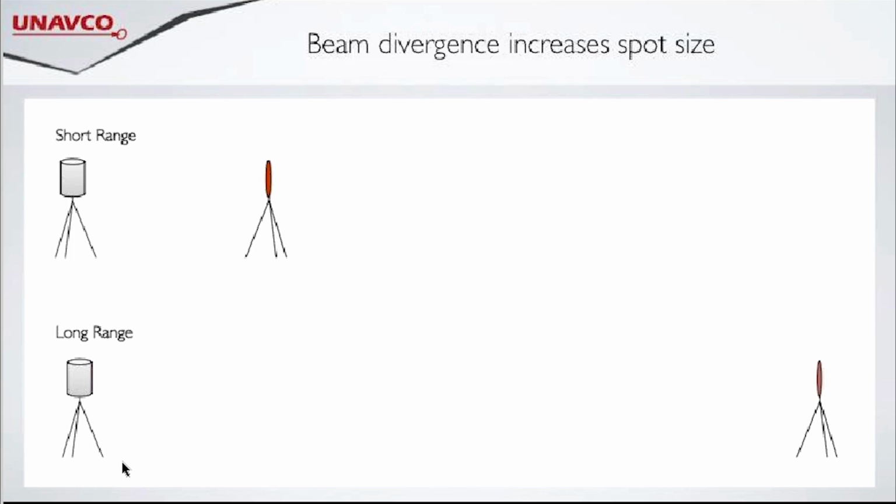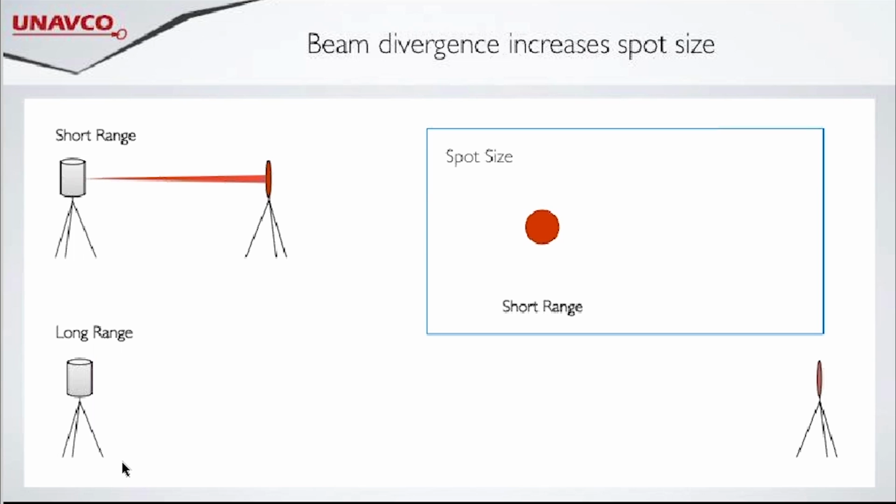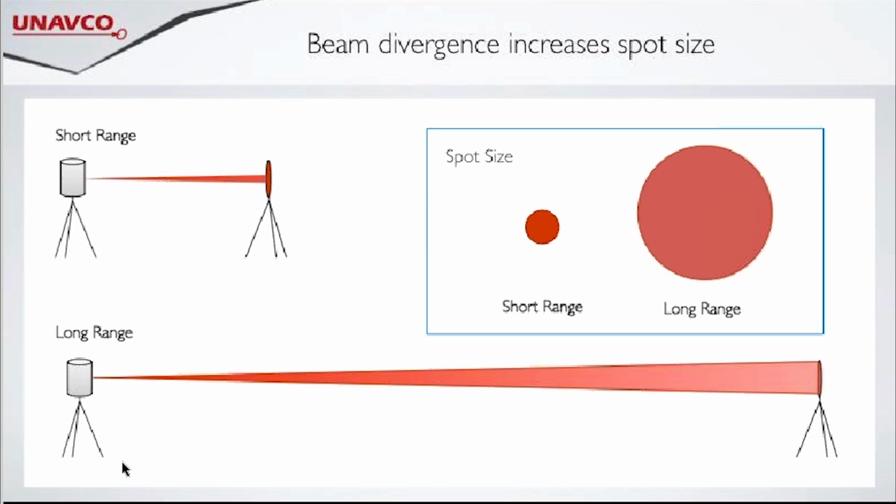Okay, so this divergence of light can seriously affect the image that is produced. For every beam that's sent out, only 1 point is collected. So for a shorter range, let's say 100 meters, the area detected is about a 3.5 centimeter circle. So you move out further away, and you have this giant area at 900 meters. It's about 35 centimeters, which could be larger than the target, and still you're only getting 1 point of return.